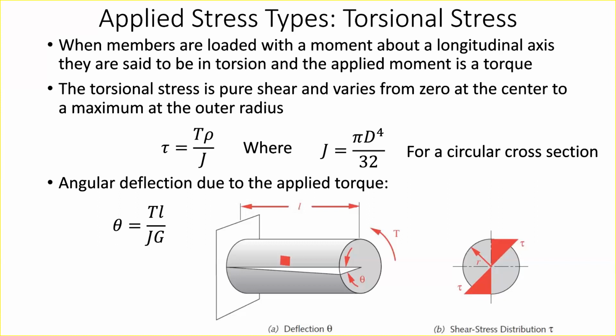So if you gave me the decision to make a solid rod versus a rod that had a lot of material on the edges, like a tube, typically if you're trying to react a very strong torque for as little weight as possible, you would prefer the one that has the mass concentrated on the outside as opposed to the middle. Because at the end of the day, I'm just failing on the outside of the part here, right?